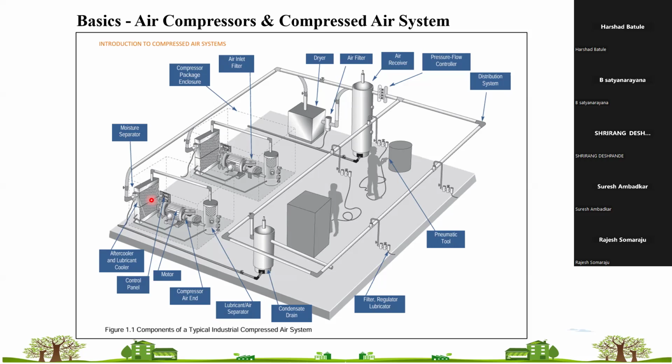So the major load will be on the after coolers, then air dryers will be there. The work of the after cooler and air dryer is to remove moisture from your system. So, what is the recommended humidity in a compressor? Is it a standard or does it change from industry to industry? No, it does not change. It does not have any recommended number. So for the instrument here, you don't require a single droplet to be near that particular instrument.